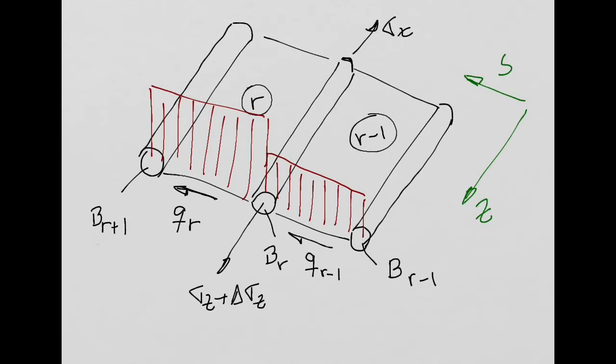What I'm going to do now is study the equilibrium of this boom in the middle, which I'm going to put here in green. Don't forget, my aim is to calculate the variation in the shear flow when I cross the boom. So, if I study the equilibrium of this boom in the middle, I will be able to calculate that variation in the shear flow, okay? That's what I'm going to do.